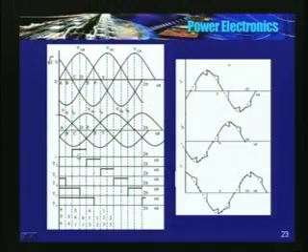See, I will show you the phase voltages. After 30 degrees, somewhere at this point, see, VCN is becoming 0. So T5 turns off. So I have stopped, or this is the boundary for T5 gate pulses.